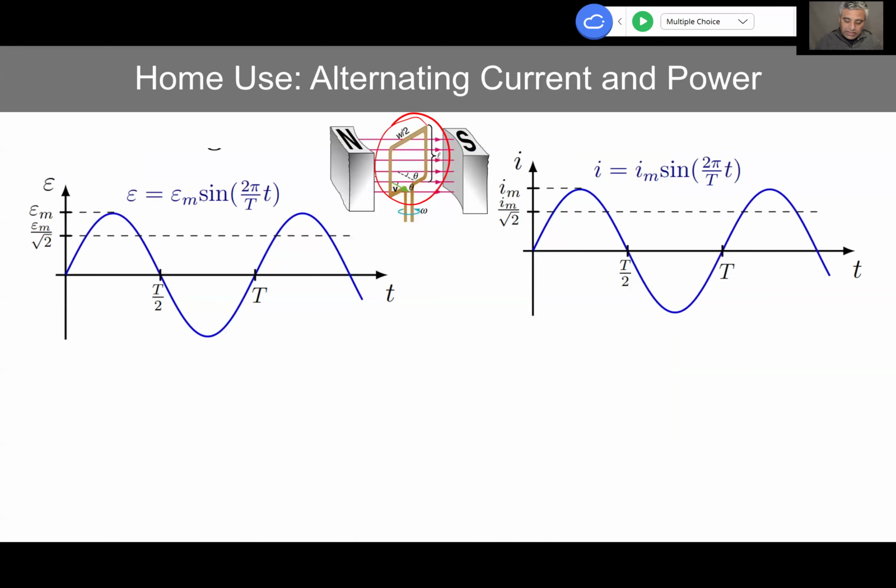So when the coil is rotating, it produces this EMF that is changing as a sine function or cosine function, right? A sinusoidal function. It oscillates, goes to the maximum value, and then goes to the maximum value on the other side. I wouldn't say minimum value; the minimum value would be 0 here, this line, right? And this value over here is the maximum divided by square root 2, so slightly less. So where is that number coming from?